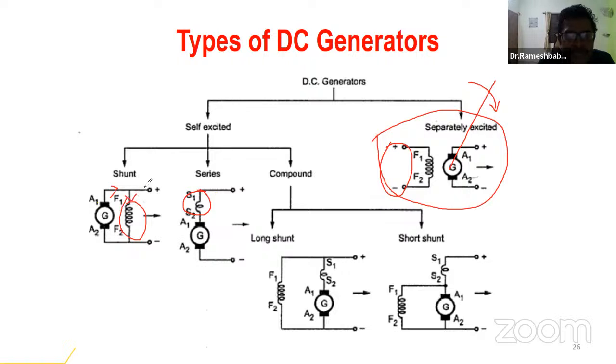At the same time, we give the current to the load. So now the small flux builds up. For example, the field current is in the range of 0.5 ampere initially, now 1 ampere, 1.5 ampere. Like that it keeps on building up. So we are not at all providing external DC supply to energize the field winding. It's called self-excited.